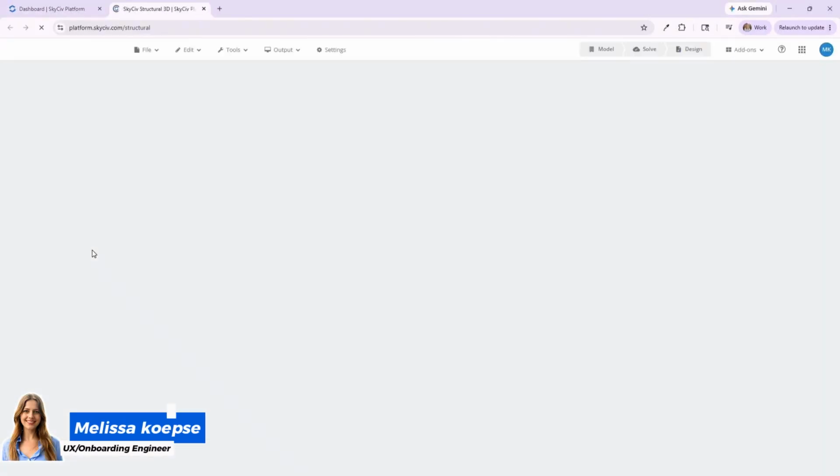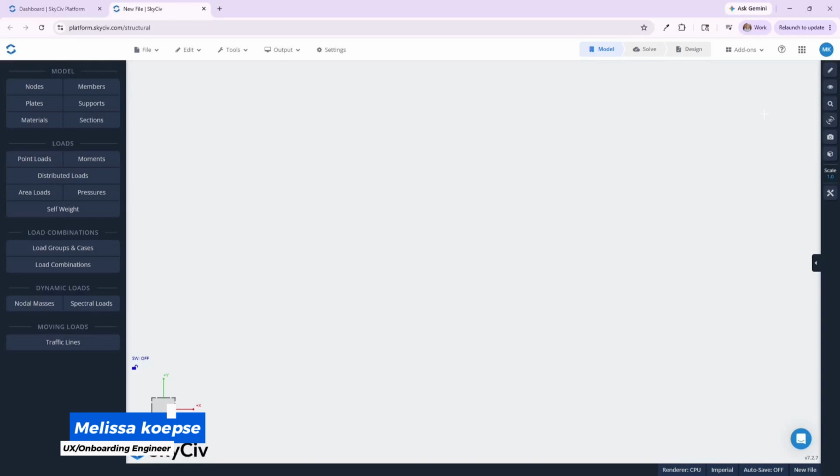In this video, I'll walk through a quick before you solve checklist in Structural 3D so you can avoid common solver errors and get results faster. Before you solve, make sure your model has members or plates, supports, section and material properties, and loads. If you have plates, they must be meshed. Then we'll run repair model to catch issues before solving.